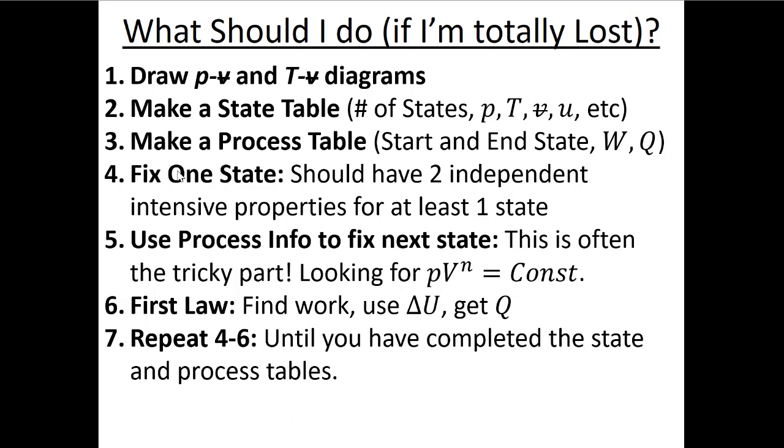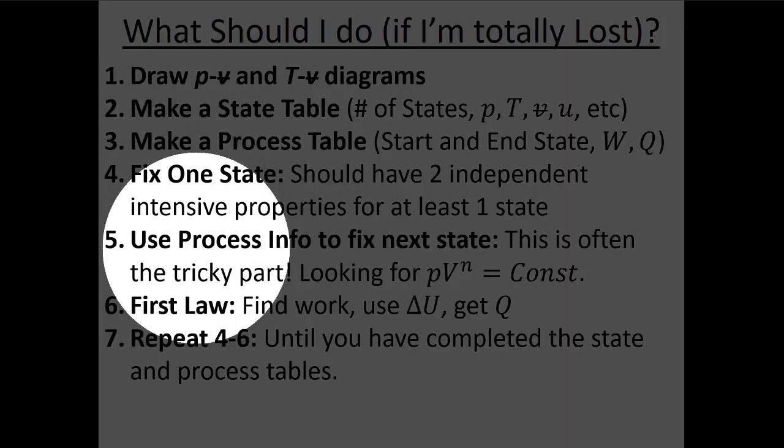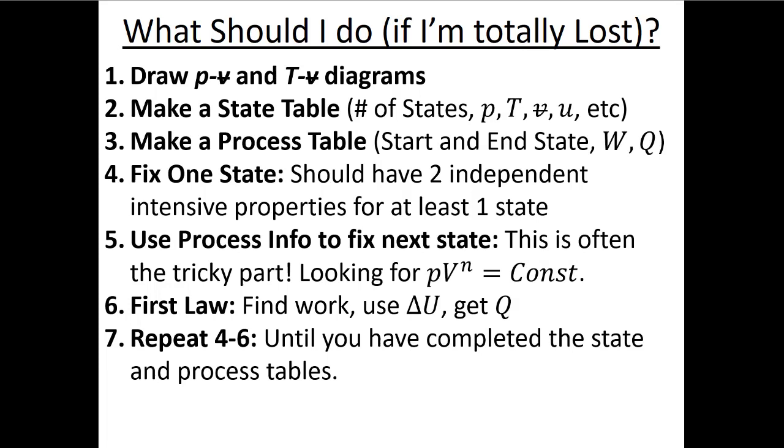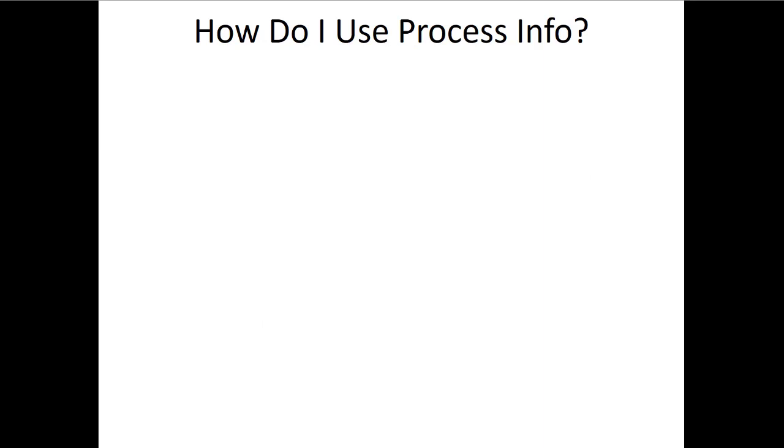Right? Again, I guess the caveat that's maybe not here is that it's nice, I think, to start with the first law stuff so that you can see what are the variables you need to fill in on your state table, so that you don't get to a point where you're just filling in the state table and taking up time with variables that you don't necessarily need.